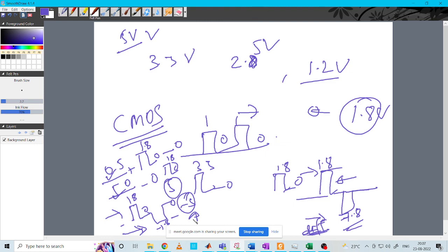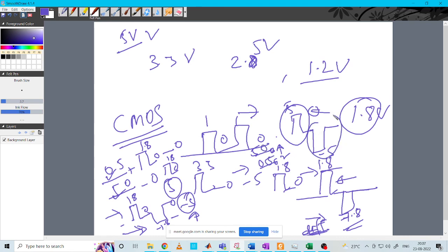So let's say you have inverting and non-inverting input, correct. So you have, let's say, 5 and minus 5. Don't think as if the amplifier, or the output circuit, is actually pushing minus 5. No, it can be that you have two lines and you are taking the difference. So once you give 5 here and 0, you get this voltage, and once you give 0 and 5 here, you get the opposite voltage. Okay? Okay, thank you, sir.